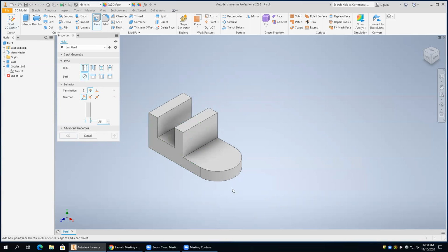Then I want you to come down and touch the bottom edge of that arc and just click on that, and you should see a hole placed there. Everybody see that? It just put it wherever it wanted to. So what you're going to do is touch the edge of that bottom arc again, and it should kick it over into the middle position. In other words, it's saying line it up with the center. The center of the hole is the center of that circle now, or that edge. Okay. That's really a neat feature right there.